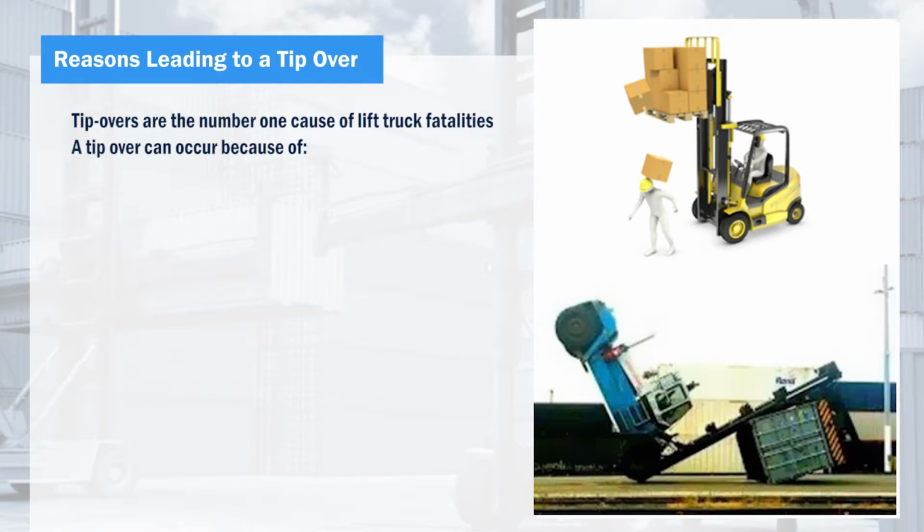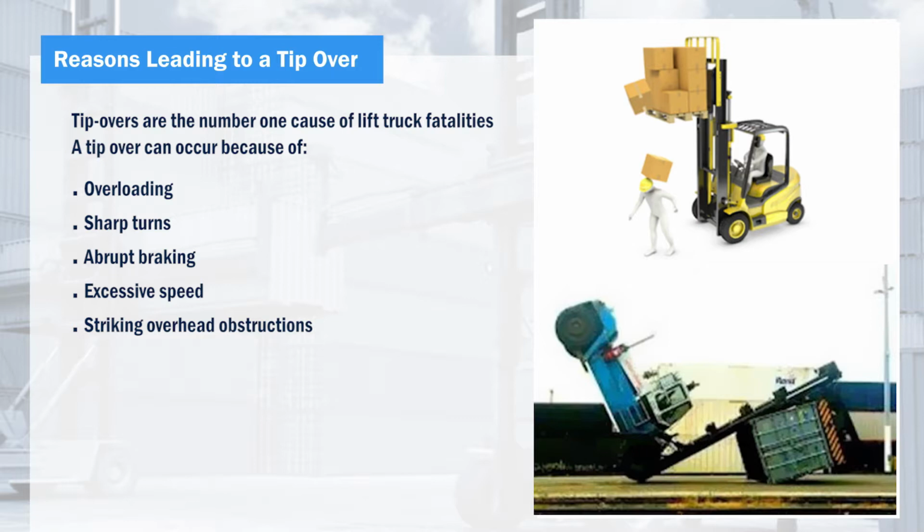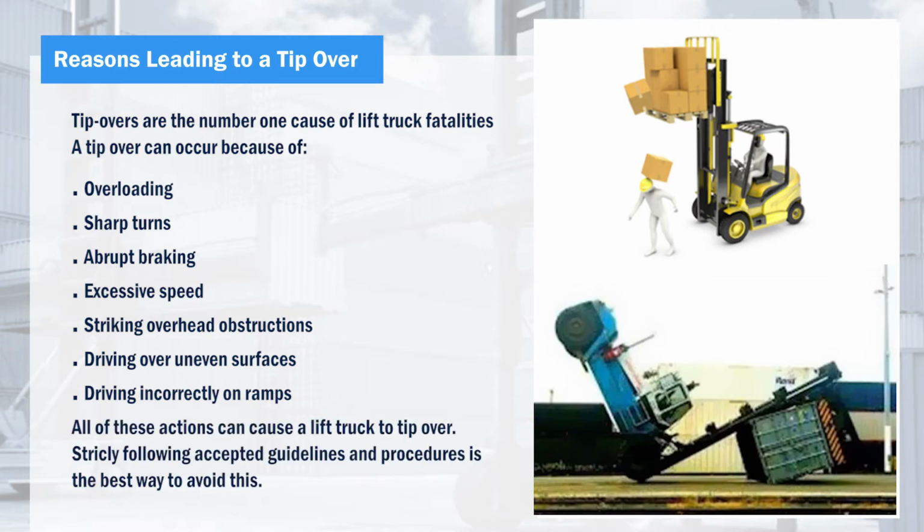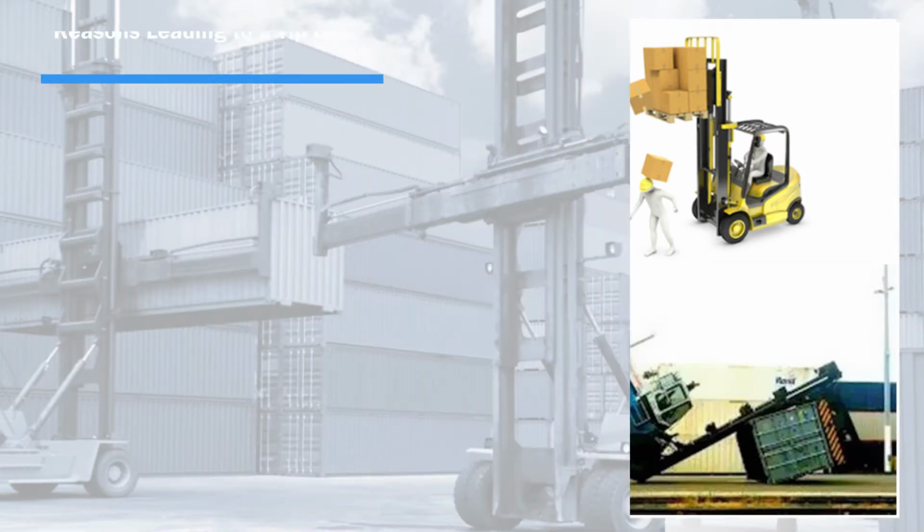Tip-overs are the number one cause of lift truck fatalities. A tip-over can occur because of overloading, sharp turns, abrupt braking, excessive speed, striking overhead obstructions, driving over uneven surfaces, or driving incorrectly on ramps. All of these actions can cause a lift truck to tip over. Strictly following accepted guidelines and procedures is the best way to avoid this.